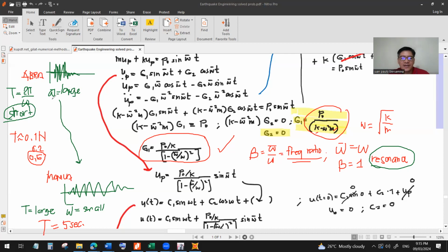Okay? Whereas when it reaches Manila, it's already small, therefore it will resonate with relatively large period structures. Okay? So that's why you see, when there's a seismic wave, there are times that high-rise buildings sway, and the water in the swimming pools on top spills.